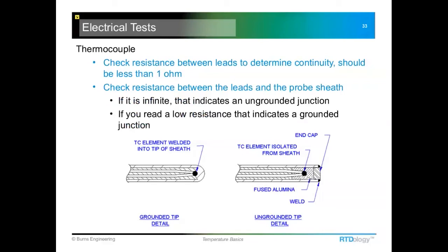Probably a good idea too, just to measure the resistance between the two lead wires too, just to make sure you do have continuity and that the probe didn't actually fail, or that these wires didn't break internally.